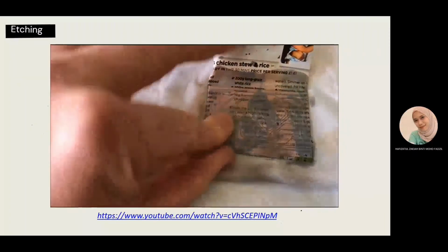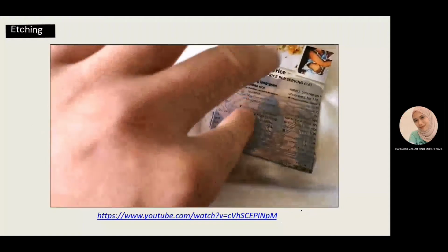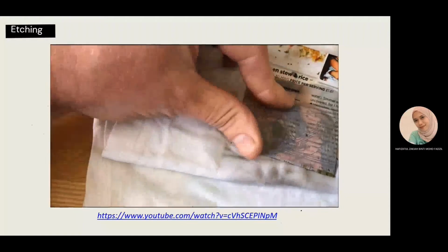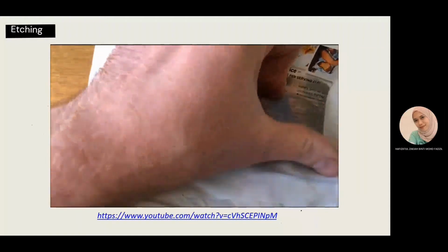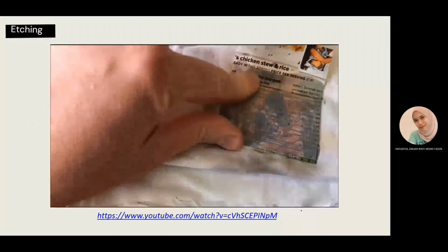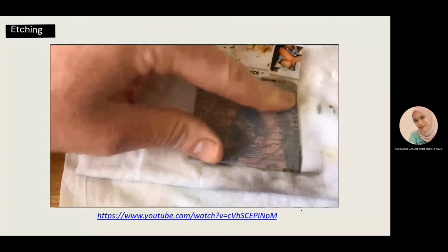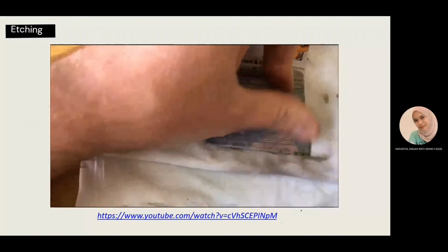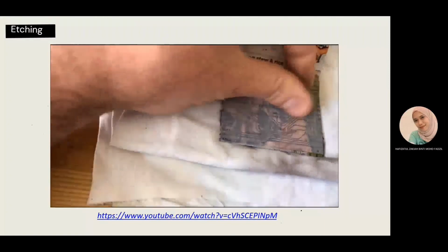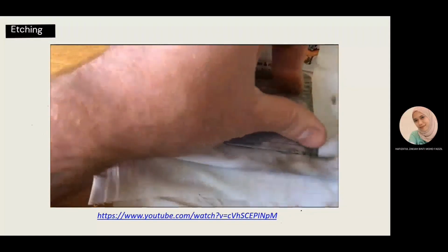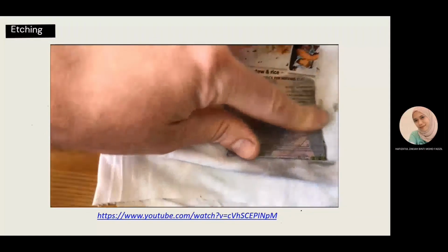To transfer the image onto the copper board is this nail varnish remover or nail polish remover. It works absolutely fine. I used to use it on the silkscreen layer and just decided to give it a go on the copper board layer to save all the time of ironing and heat transfer. And it works. So let's give it a go.